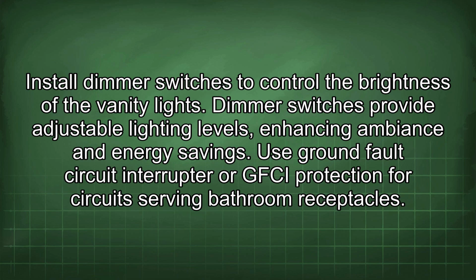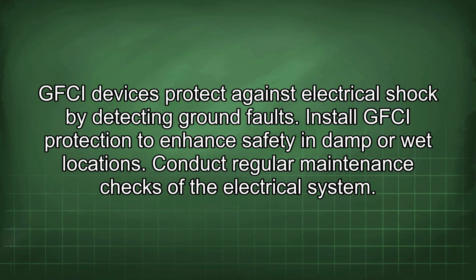Use ground fault circuit interrupter, or GFCI, protection for circuits serving bathroom receptacles. GFCI devices protect against electrical shock by detecting ground faults. Install GFCI protection to enhance safety in damp or wet locations.